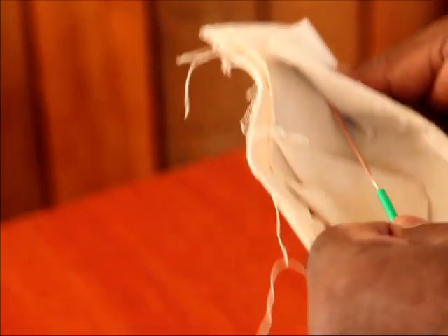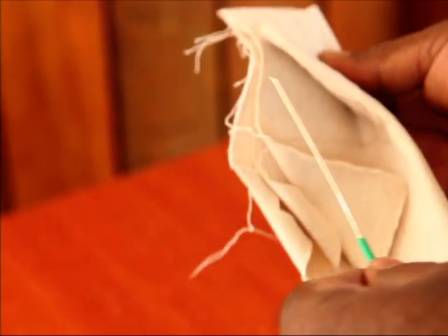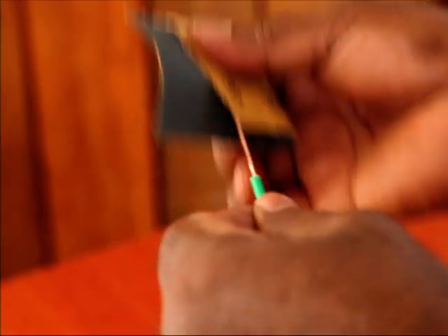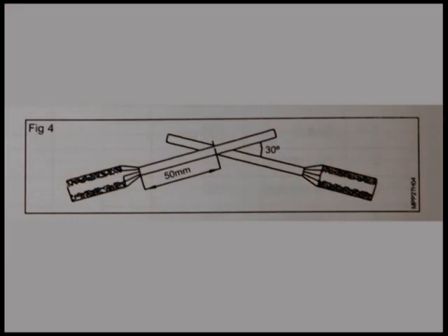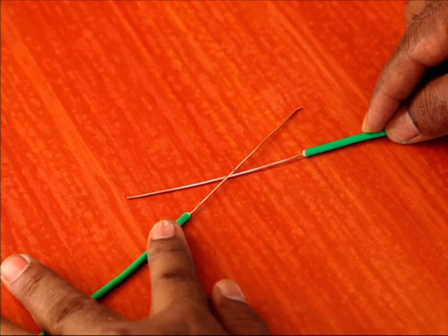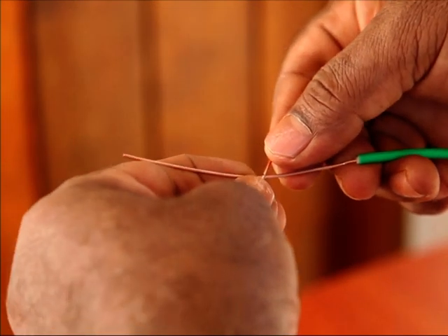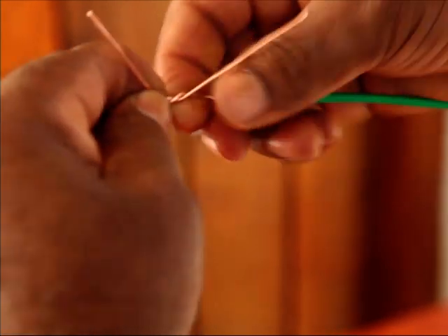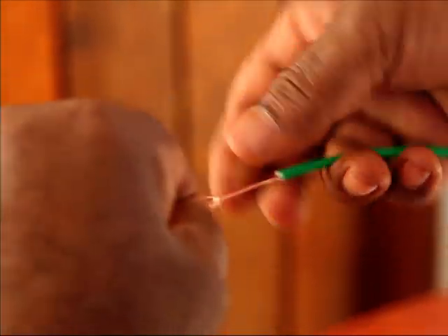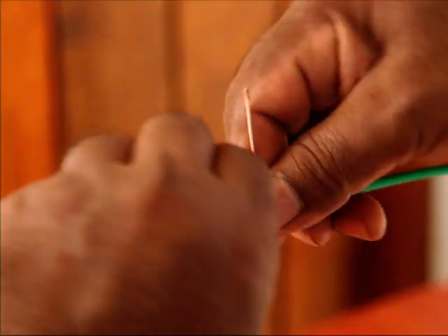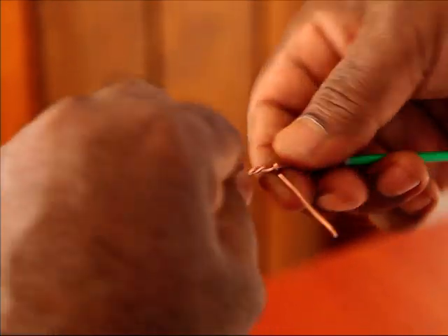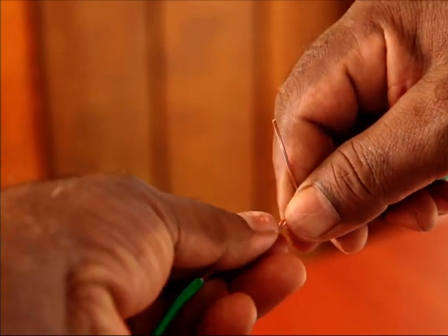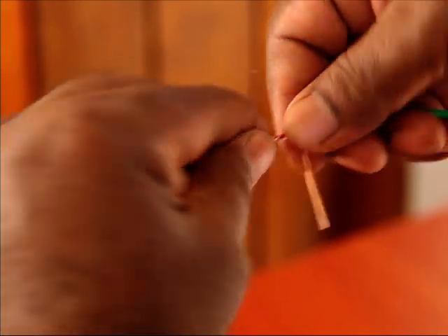5. Clean the ends with the help of cotton cloth. Use smooth sandpaper if necessary to clean the conductor. 6. Place the conductors together about 50 mm from the ends. 7. Twist them tightly round each other in the opposite direction. Each twist should contain about 6 turns. Each turn of a conductor should fit closely to the adjacent turn.